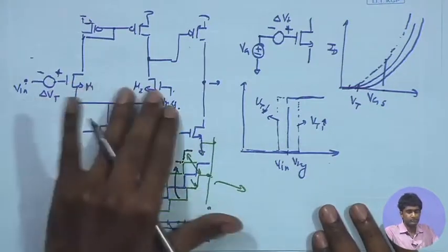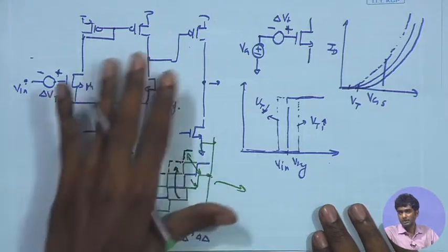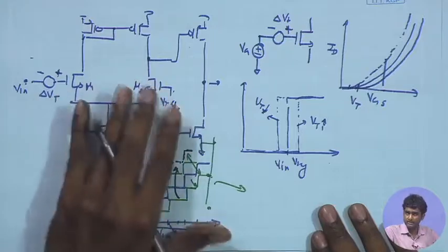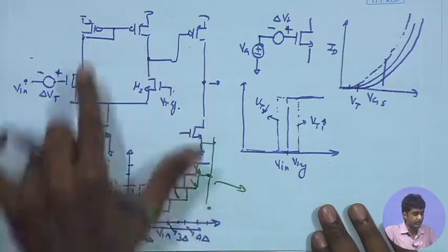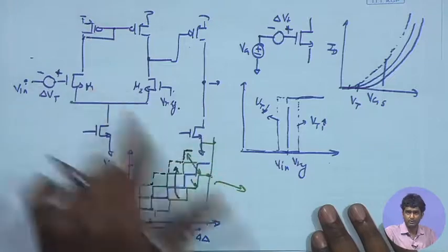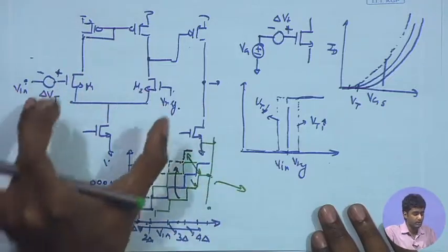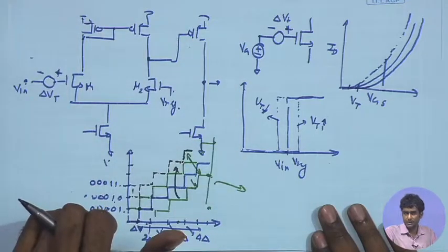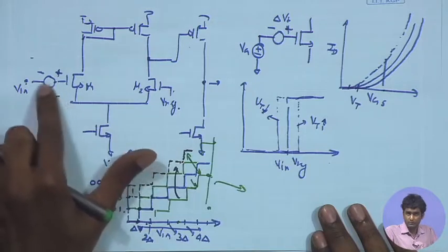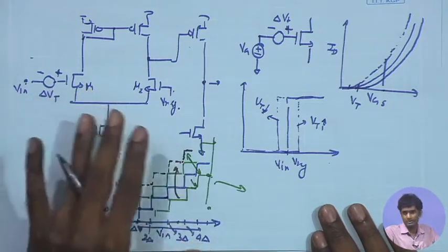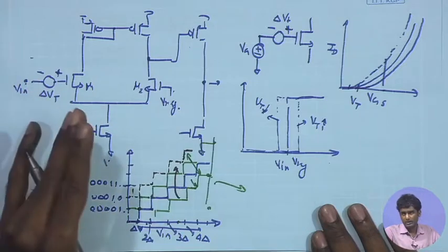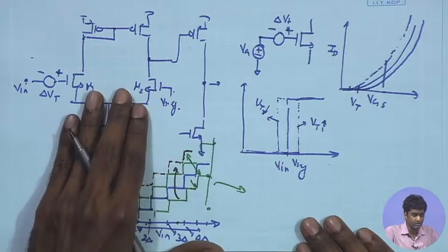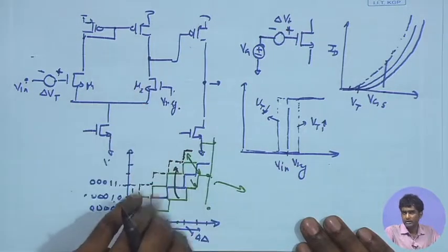In general, if you are going for the sizing of the transistors and trying to reduce it to a few micrometers, the mismatches can further aggravate. You can have mismatch between the two PMOS transistors over here, and the NMOS over here, and as a result the overall effective mismatch between the two transistors in the pair can lead to a larger effective offset voltage. A good value can go all the way up to a few tens of millivolts. If the fabrication layout is not done properly, the mismatch can be pretty bad.